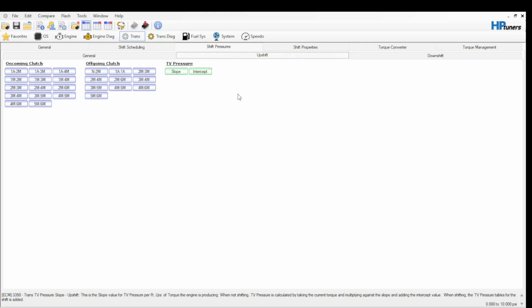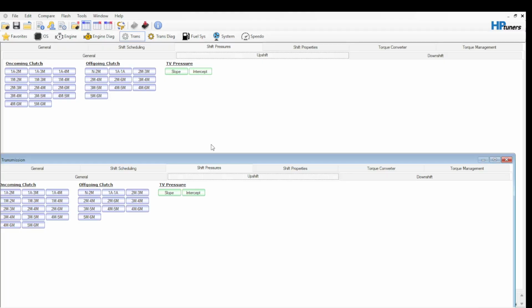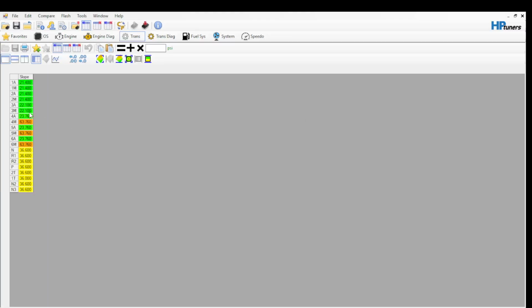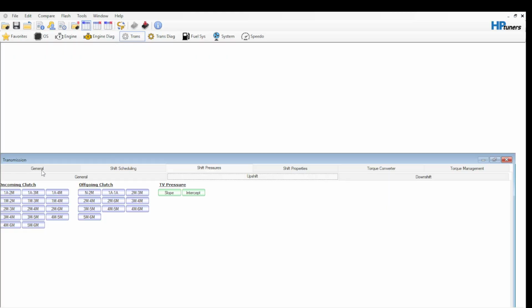That is the linear interpolation, because what you also have here is the intercept. So if you're also in third gear, it actually means you're going to be pushing that solenoid at 134 psi, because it's 112 plus 22.1. Now, why would they do it this way instead of just increasing the slope, right?